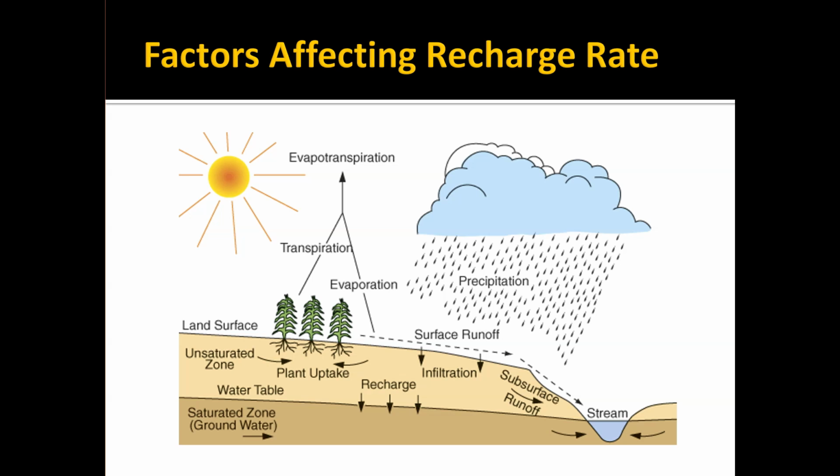So those things need to be factored in as well. But again, it's a pretty simple and straightforward package. Just estimate your recharge, put it in the right units, and assign a value for each cell in the top layer of your grid typically, and then you can begin to use the recharge package.